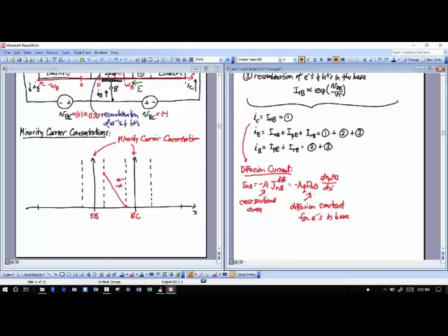with respect to x. Where n_p(x), like we said last time, is nomenclature for the electron concentration in the p-type region. Okay, exact same formula that I used for the diode. And I'm going to do exactly the same thing that I did for the diode. To get the slope of this, all I need to know is the concentration at this point and the concentration at that point.